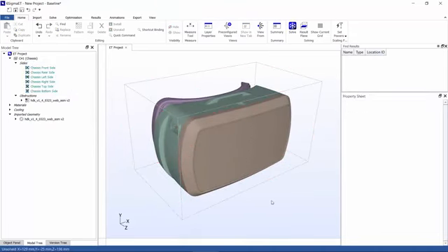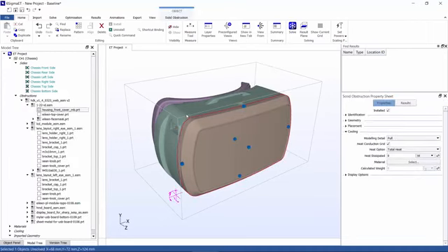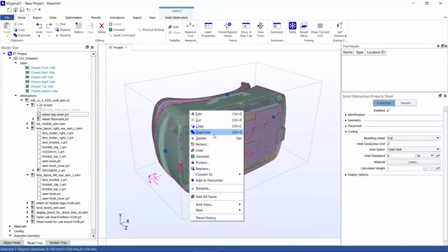Okay. So when you go to clean up a model, you typically want to look for small, detailed objects that may not be as relevant to the thermal analysis as other objects. Things like screws, buttons, maybe detailed brackets in areas that are away from major heat sources. All these things can be looked at and considered for helping to reduce your model size and make your life a little bit easier when it comes to the solve. And so for now, I'll go ahead and look behind the curtain here and remove these covers.